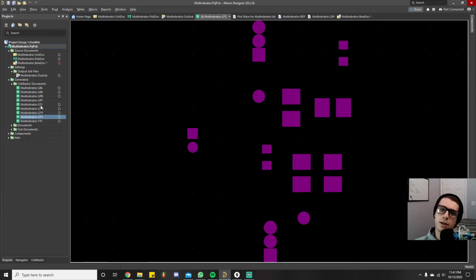So the way the layers are set up, you have your signal layer. This is a 2-layer board, right? So we have bottom layer, bottom solder mask layer, and then paste bottom, paste mask. So you have a signal, solder mask, and paste mask. Those are the 3 things that go on each side of the board, and then you have some internal stuff for vias. This is what the Gerber files look like if you're just curious.